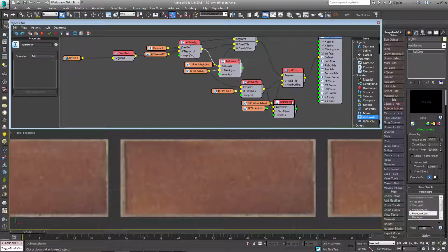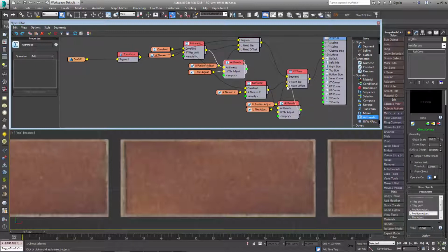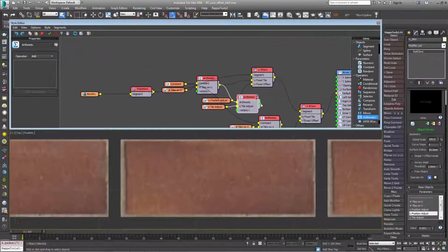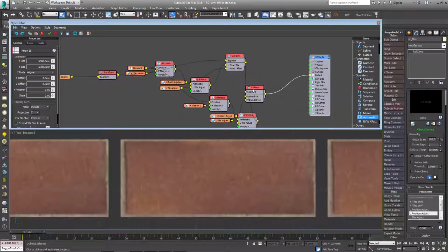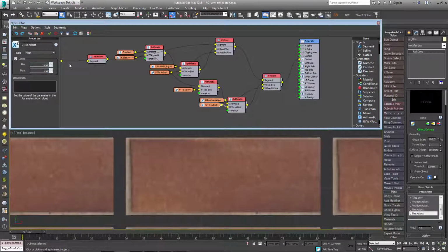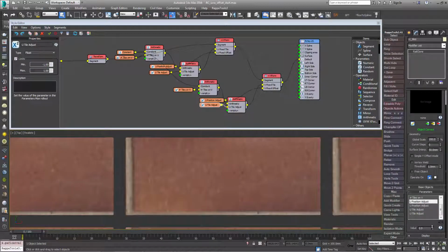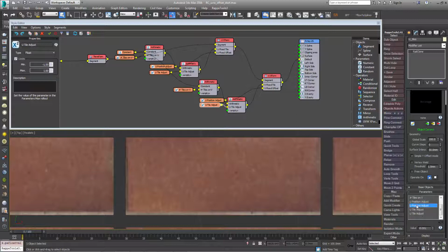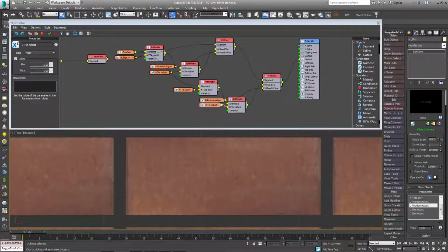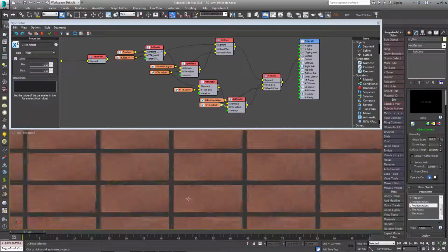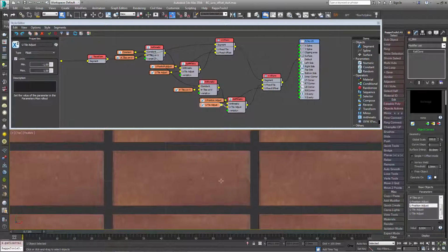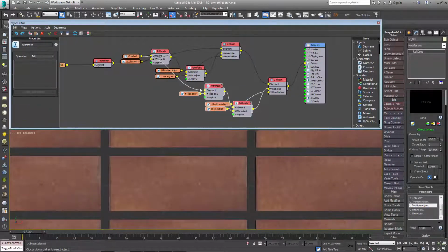Finally, wire these arithmetic nodes to the U or the V fixed tile inputs on the UVWXForm operators. You can now adjust these new parameters so that only the tile shows on the segment, clipping off the joints. Now that we've isolated a single tile, we can randomize the offset to select the others in the source texture. To do this, we'll use the UVWXForm's randomize features.